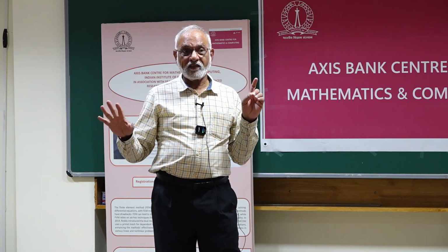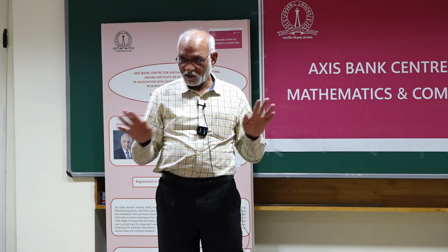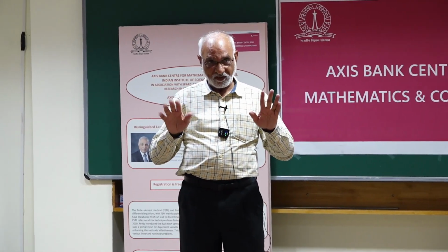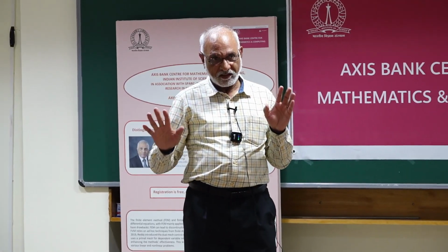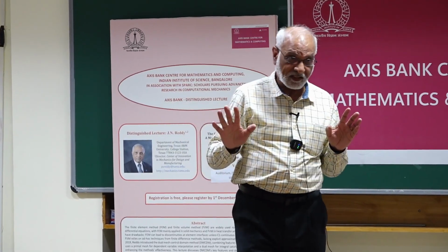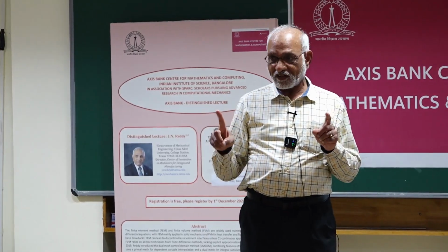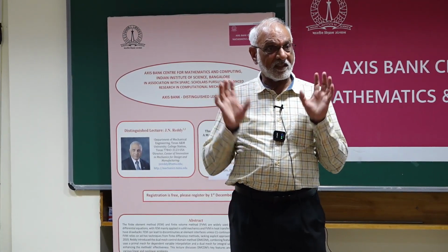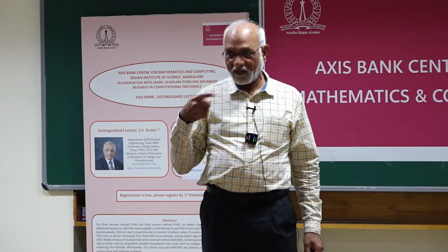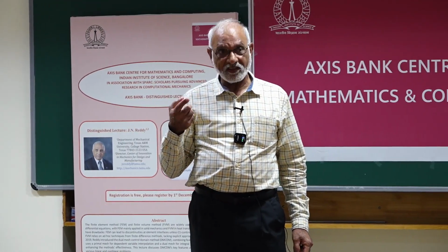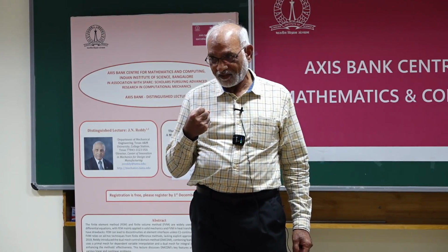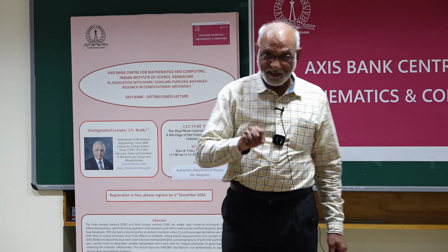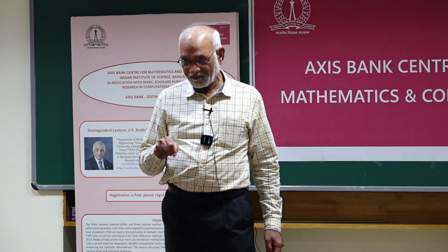So your constitutive equations are rate dependent, there is no problem. Okay, so that is where the problem comes. If you don't use rate-dependent constitutive equations in solid mechanics, then you have to convert the velocity into displacement relations in a consistent way, meaning material time derivative, okay, which is going to bring nonlinearity automatically. Additional nonlinearity in addition to whatever constitutive nonlinearity is there.